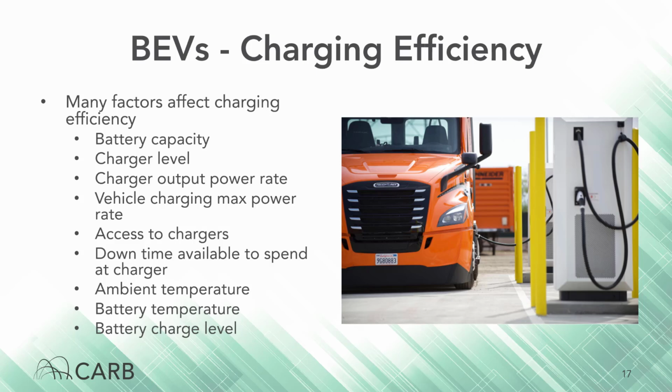I'll talk a bit more on that in a moment, but because of this, it may be more efficient to charge the vehicle to 80% rather than all the way to 100%, and then charge it periodically during use through opportunity charging or downtimes like mandatory breaks and lunches. Charging a battery 3 or 4 times a day to 80% can take less time than charging it to 100% once or twice, while still resulting in the same or greater overall range.